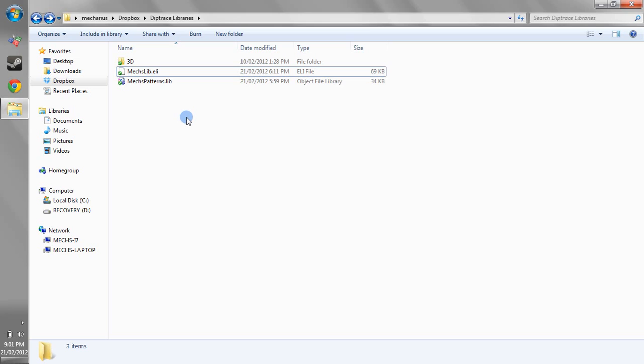Obviously, you've got patterns, which are the physical footprint of a component and show where the solder pads are, where their drill holes are, and if there's any silkscreen that's defined. And then you've got your components, which are the electrical description of an item, which show the pins of the component, the names of the pins, and show in a schematic how they're connected to other components.